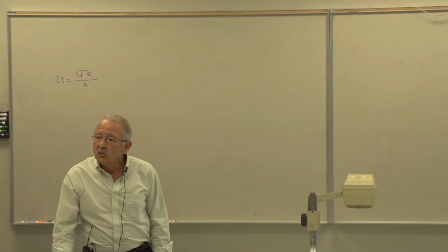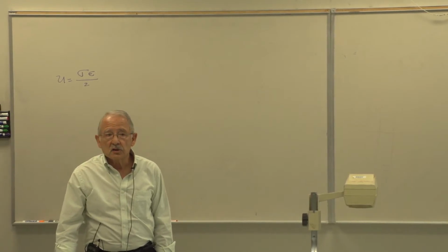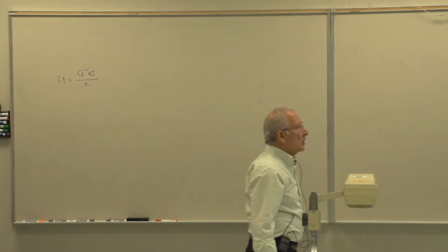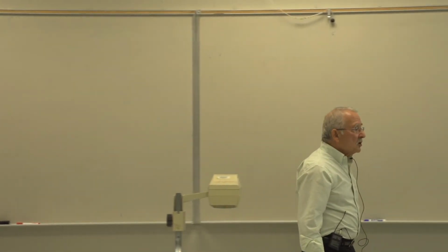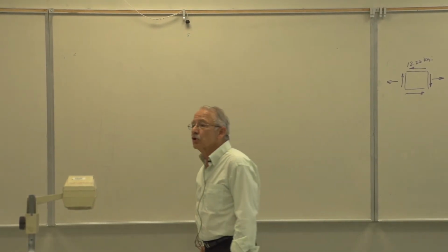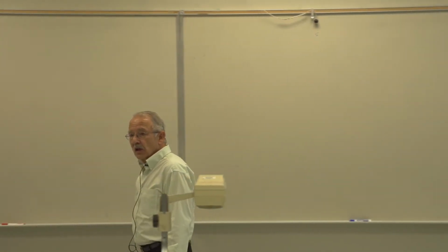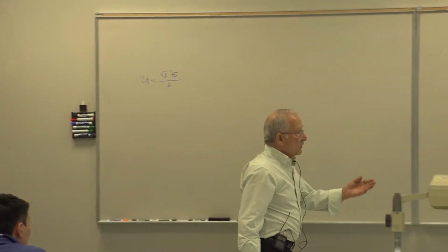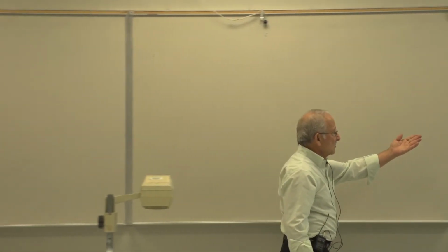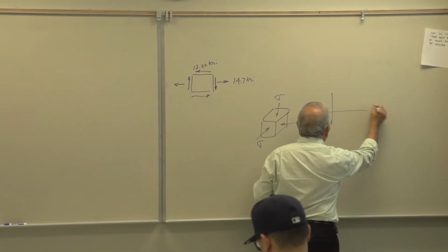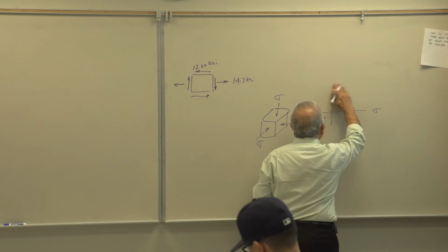And we also know that yielding, which is the type of failure that occurs in ductile materials, is the result of shape change or angle change or shear stress, and not volume change. In fact, if I draw Mohr's circle for this,